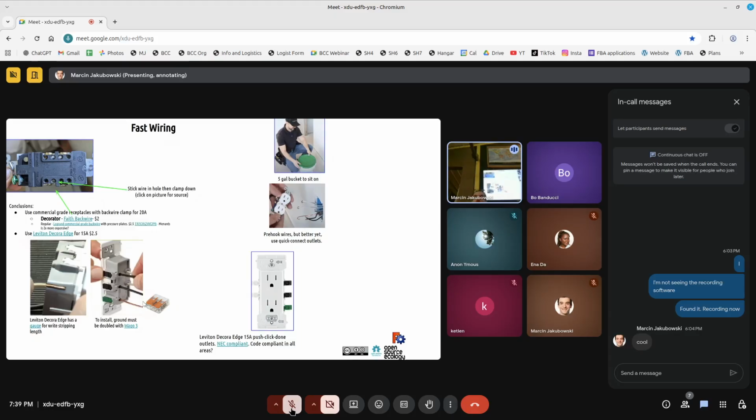Like say you want to run your cooling, whatever your air conditioner, that gets you down to a comfortable temperature. Well, you can get that out of the soil, a consistent, say, 60 degrees. That's the goal. You bury it. If you've got that temperature around, you can use that directly for the cooling part, for example. Yeah, that's an example of direct geothermal as opposed to geothermal heat pumps where they're exchanging heat or cool between underground and your home environment.